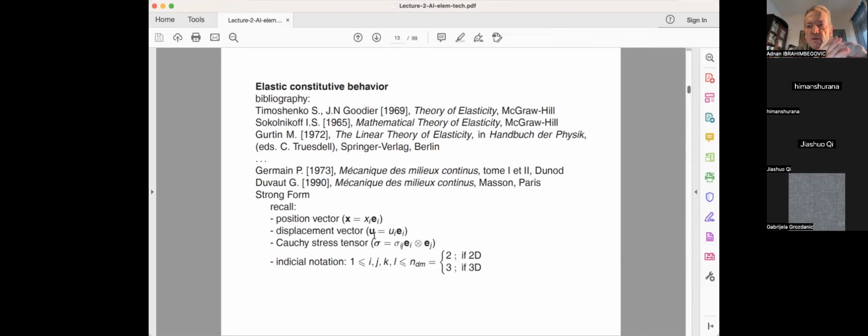We are talking about small displacement gradient theory, where the initial configuration could be the one that is used to represent the true deformed configuration. So basically the stresses are then the only true stress that appear on the deformed body. It is a tensor of the second order, which has component sigma ij. It appears at first that it has 3 by 3, that will be 9 components, but as I said, due to the symmetry that follows from the moment equilibrium equation, sigma ij is the same as sigma ji. You reduce down to 6 components of this kind.